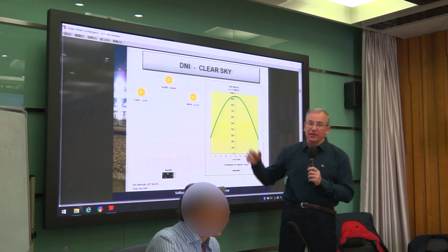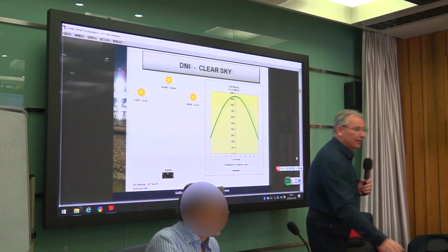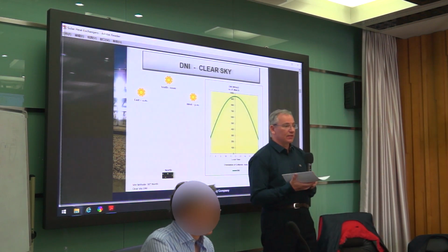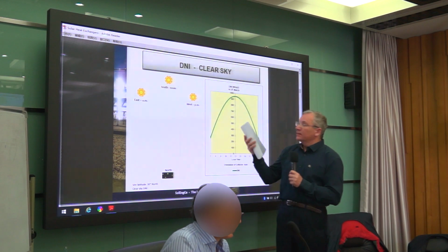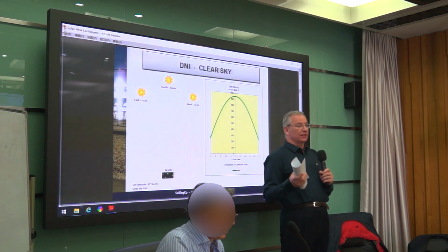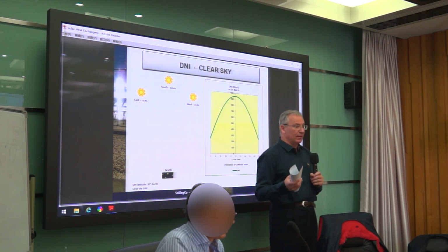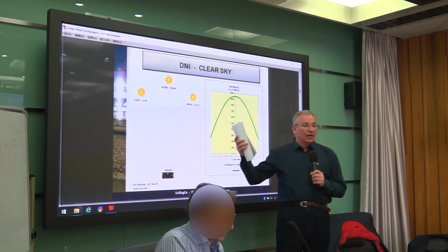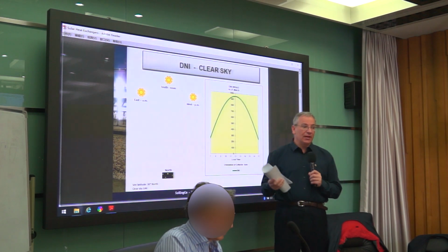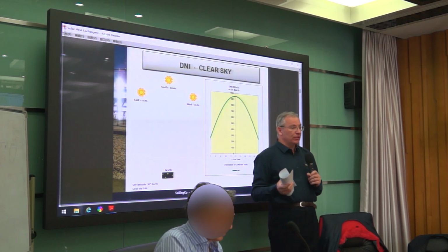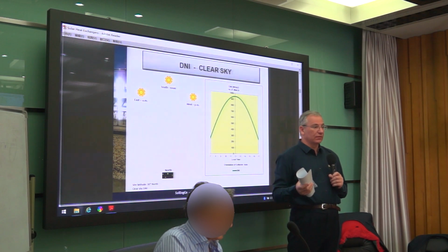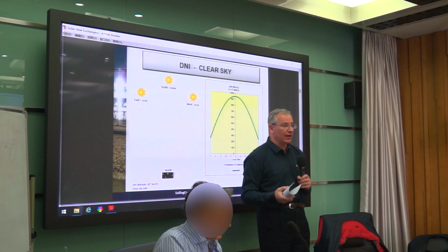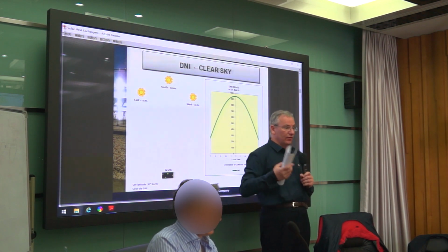This line seems to be clear to everybody, but let me explain. Firstly, we have a clear sky. This is the clear sky, and we even discuss here why 1000 watts per square meter has been chosen for the reference case. Because we have on the planet very nice places at which we can reach such a high irradiation. For our presentation, we choose the irradiation 950, which is a very high irradiation.